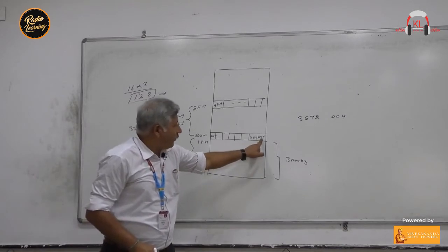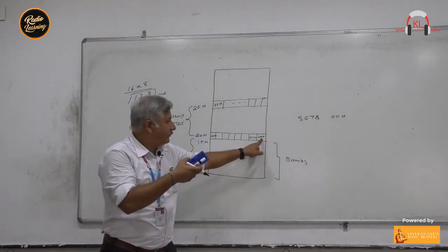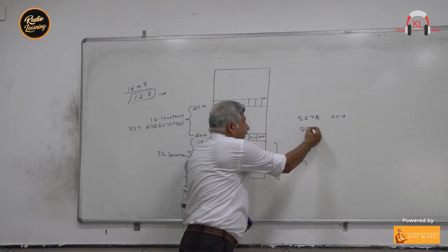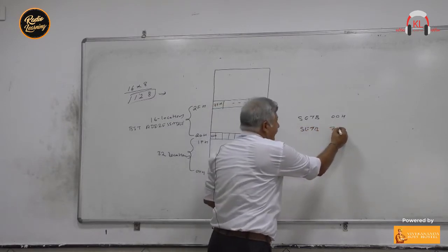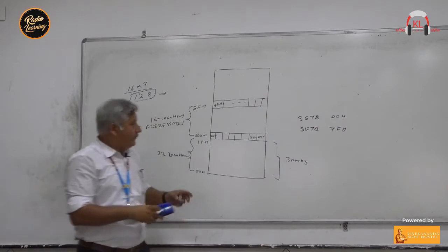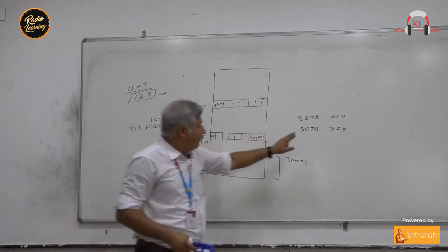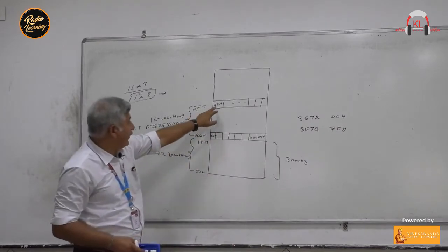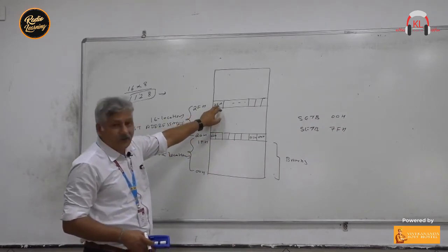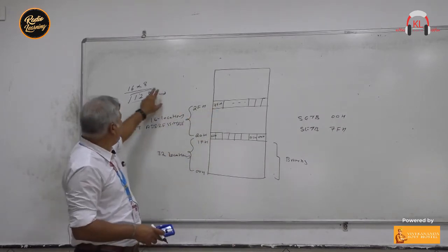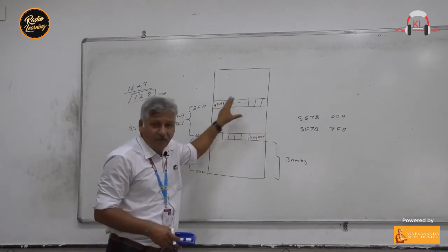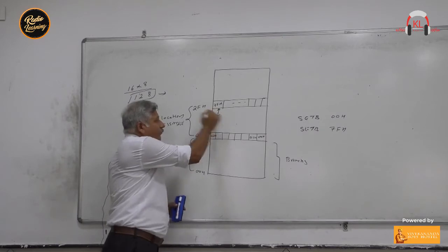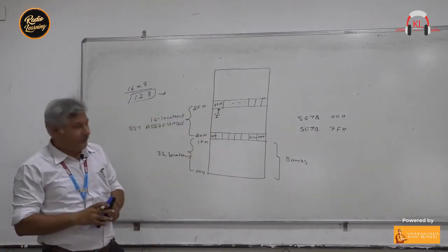This particular bit of this address will be set, right? So if you write the instruction SETB 7FH, then what will happen? The bit whose address is 7FH will be set. 7FH is the address of this bit. So out of the 128 bits which are available here, this particular bit will become 1 with the help of this instruction, right?